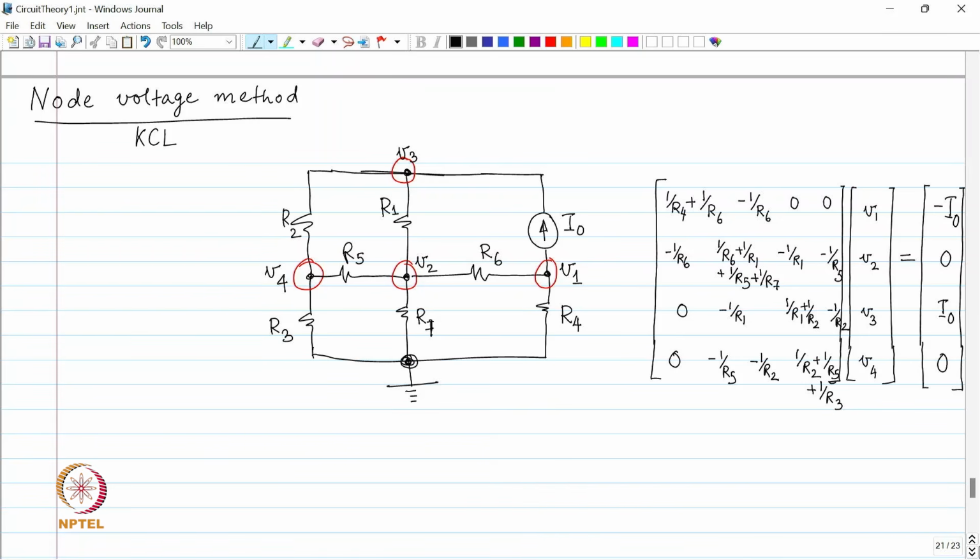Okay, very good. Your name is? Nishant is absolutely right. So, the diagonal elements, we always started from the diagonal element, right, and then wrote the other elements as negative. Okay. So, the diagonal will come to be positive, all the others will come to be negative, and the big sanity check over here is that the matrix is somehow magically appearing to be symmetric. Okay. Why, you can think about it. I will answer the why later after many more lectures. For now, this is a sanity check for you.